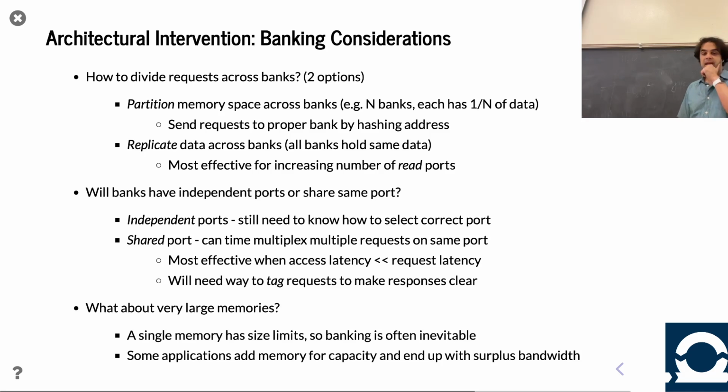If you look inside of a DRAM chip, you'll find that the DRAM architects had to play this game a lot. In order to provide the capacity, they've made certain trade-offs, and they've tried their best to not waste bandwidth internally. But if you have a DRAM chip that has gigabytes of data on it, and you're accessing 64 bytes, i.e. 512 bits at a time, most of that chip is not doing anything, right? And so how you make that work out is an interesting architectural challenge. Cool.